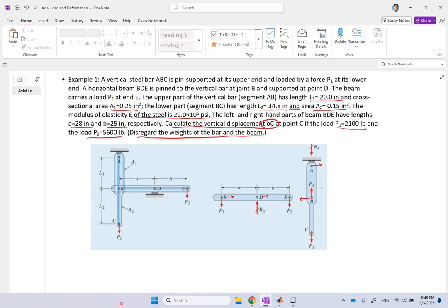Well, here, since this system is a static system, and it's not moving, if I take total moment with respect to point A, clearly this horizontal force has to be 0. That's the only force that creates moment about A. And that has to be 0, otherwise this pin is going to start rotating. Now, when that force is 0, if I take sum of the forces in the x direction, this force has to be 0 as well.